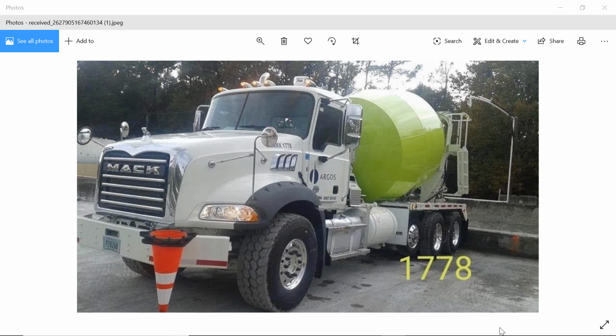The wet weight is 3.64 pounds. The dry weight is 3.45 pounds. The tare weight is 0.54 pounds. Calculate the total moisture content of the sample. Moisture content in percent is equal to 100 times (3.64 minus 3.45) divided by (3.45 minus 0.54). That is equal to 100 times 0.19 divided by 2.91, which is equal to 6.53%.